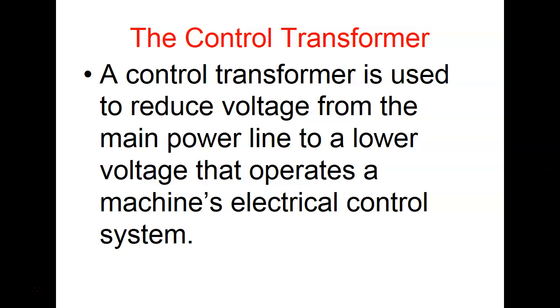But that's running a power factor of 95%, right? You understand? If they got down below that, their power bill would have gone up. Alabama Power doesn't like that. Why? Because all their equipment has to support that out-of-phase power. Out-of-phase power is not good for power grids. So that's why all these transformers are rated in VA.